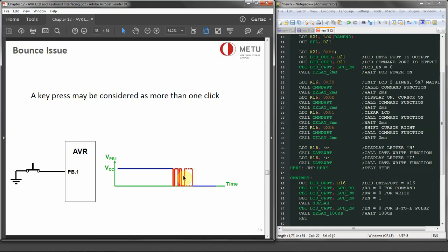What we generally say is, it doesn't matter if it's the same manufacturer, same button or something like that. It actually depends on how much force you apply and how fast you press that button, and we can have bouncing periods between 1 to 5 milliseconds.